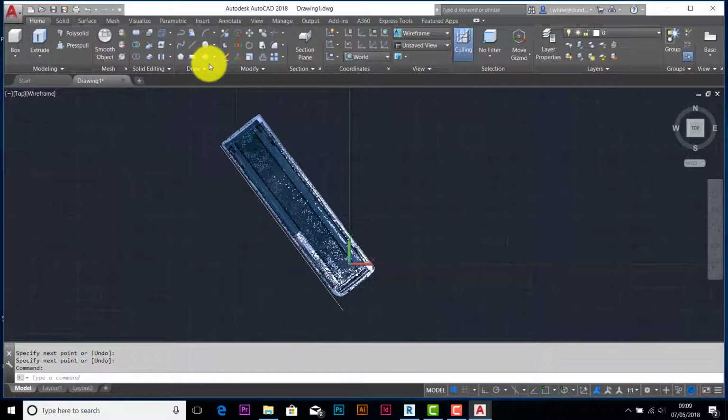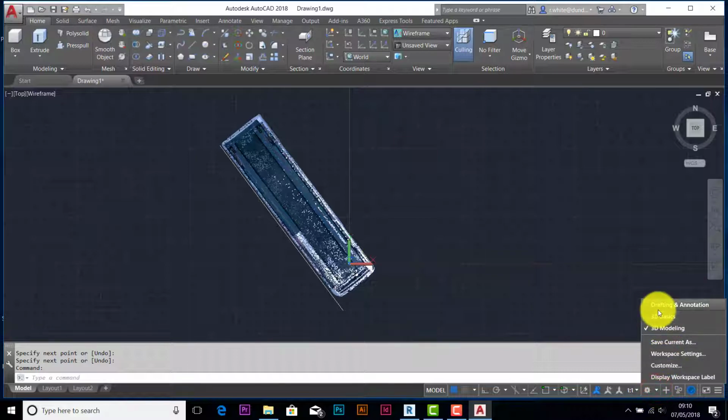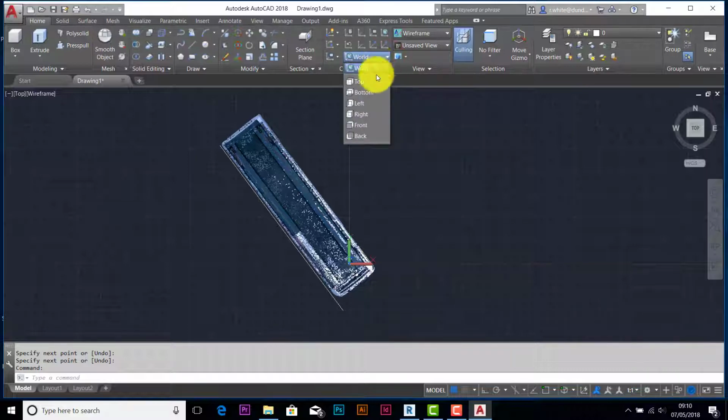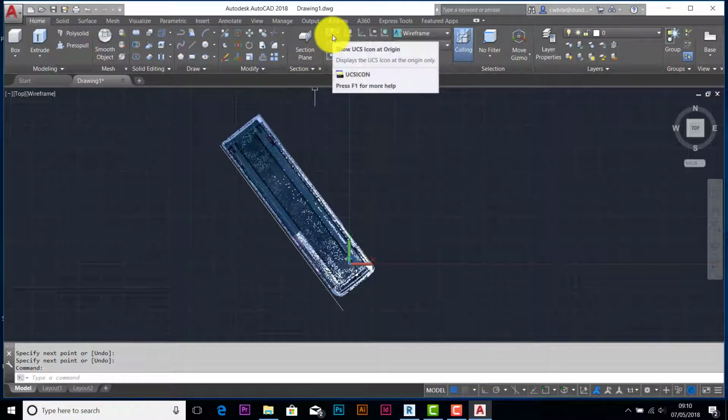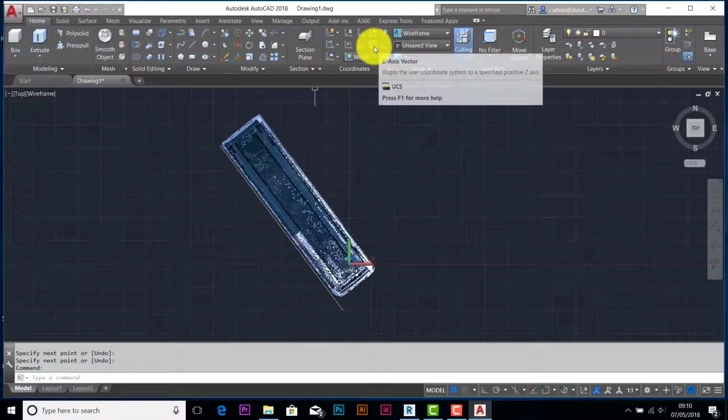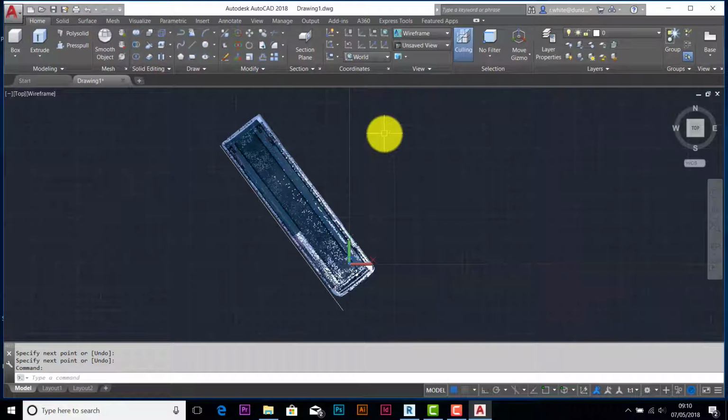If you're working in AutoCAD, change to the 3D workspace. Down here we've got the workspace switcher, and usually you're on Drafting and Annotation. If you go to 3D Modeling, then you can see this panel here, the coordinate systems. These named ones are fine for working your way around a cube, but our bus is a boxy type object that's not lined up with north, south, east, west, which is what these are basically working with. So what we need to do is line up with an object on the screen. Which one of these is it? We can pick an object. I don't generally use icons. I generally type in my commands. None of them are the ones we want anyway, so that's fine.